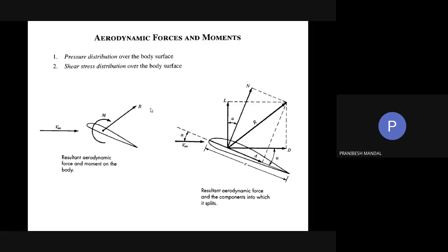Now, if you take the velocity of air very close to my object, are you going to get the actual velocity? No sir, there will be boundary layer. There will be boundary layers, there will be disturbances, right? So the free stream velocity is actually taken a bit away from my actual object.